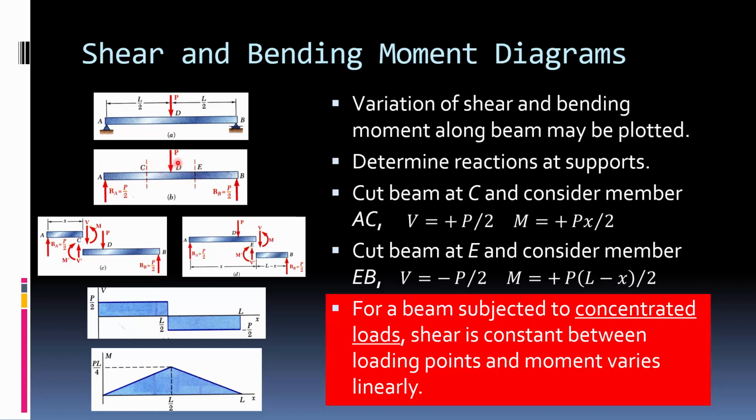And then you get on this side, and if I cut it, I can either look to this and say, well, clearly it has to go down. Remember, now we're on the left side, so that's a negative. Or you can keep on looking. I'm inclined to keep on looking at the same side. So let's look right here, right? You have a force here. I have P over 2 and P, so in total, there's still P going down. So now I have to put P over 2 going up, which is the negative shear force, which is right here. So you see that the shear is constant.